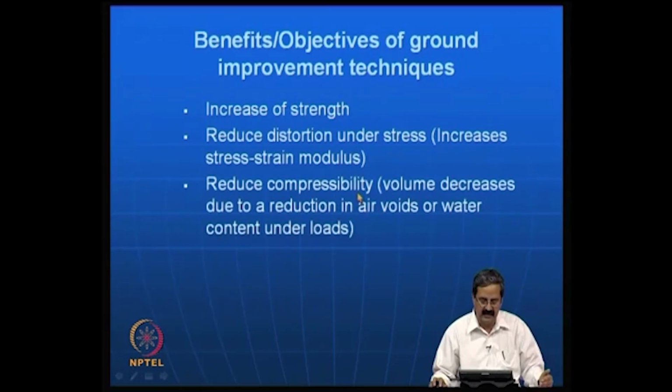Reduced compressibility is nothing but improved performance because of ground improvement, wherein the void ratio decreases. Again, one can do preloading, or fill up the air voids with some materials, so that the compressibility is less and the material does not undergo a lot of compression.